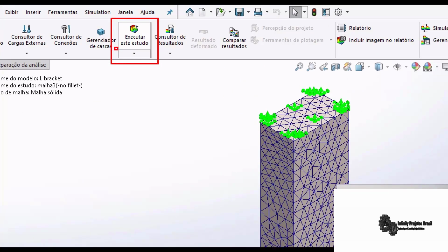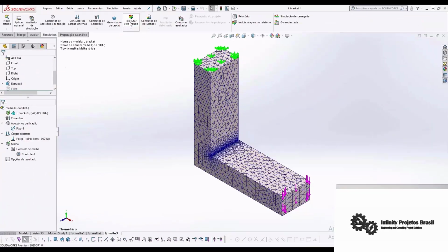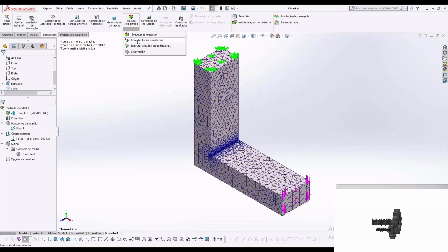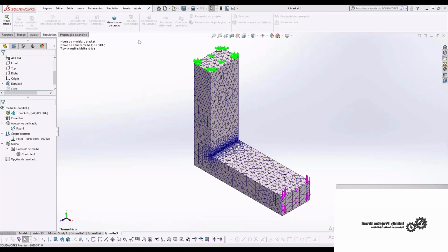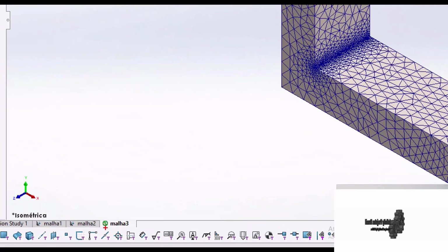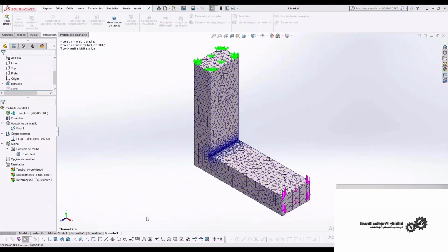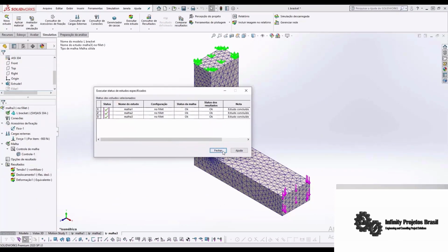If I just want it defined as a mesh, okay, so I want my limit to be my mesh, just give an OK, and then it shows for us the mesh on top of the tension graph. Here I can display my mesh. I can analyze how the mesh is distributed in relation to the deformation it is suffering. I'll do this for everyone. The other analyses are the ones already generated for us.